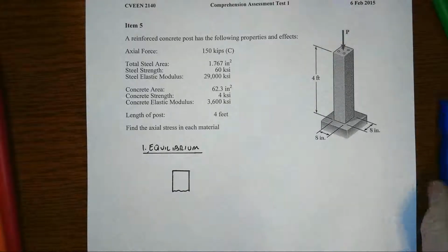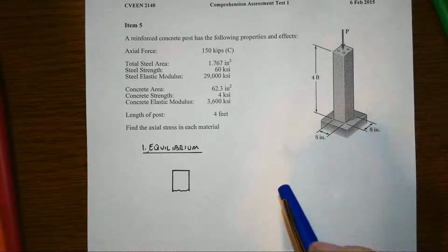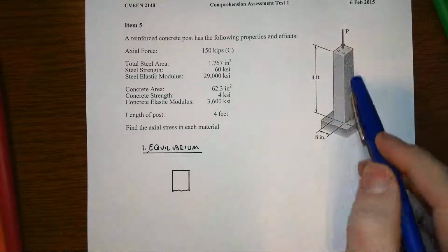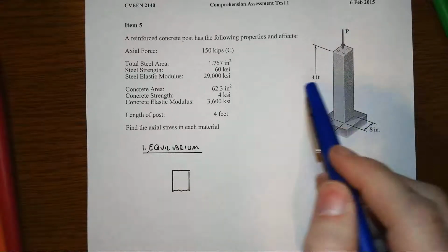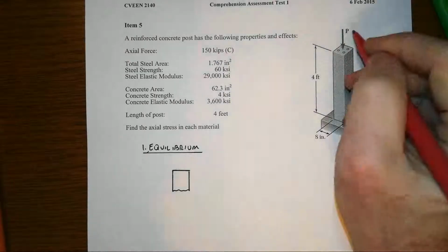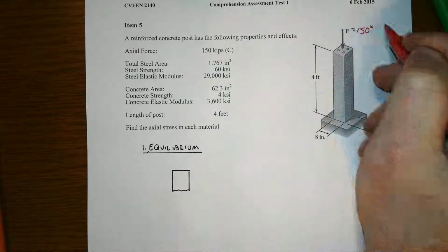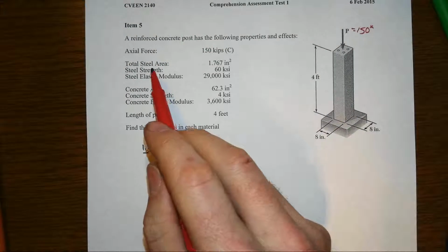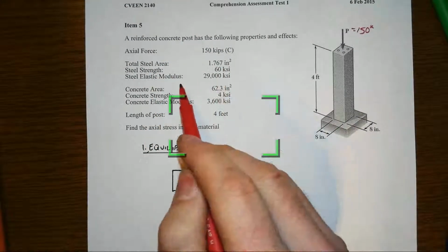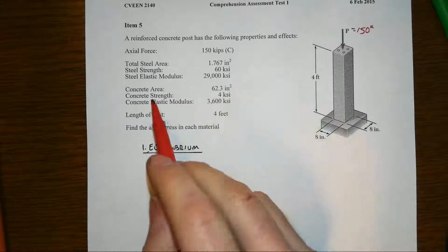In this fifth and last item on the first test of 2015 spring, we've got a reinforced concrete post that is 4 foot high. The total axial force applied to it is 150 kips, forcing compression, and we're told that we have a total steel area of 1.767 square inches, steel strength of 60 ksi, elastic modulus there, concrete